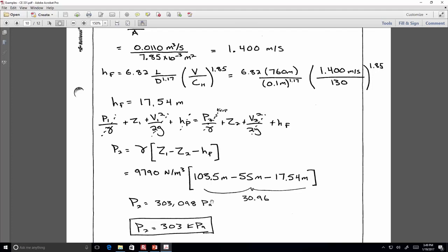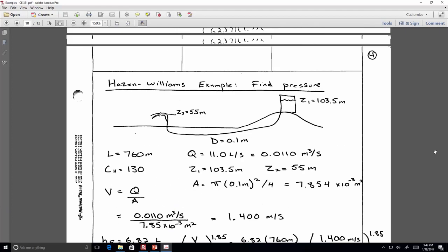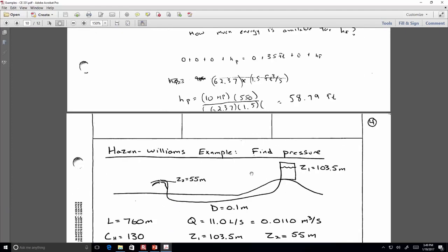I know in fluids you told us to assume 9810. Now where this is outside, are we supposed to assume 9790? Well, as long as you just state what assumption you're making, that's fine. There are different arguments to be made. The water coming out of groundwater, or out of a pipe that's underground, is probably going to be pretty cool, maybe around 55 or 60 degrees, so you could look up the unit weight for that. The 9790 corresponds to a little bit warmer water, and I think the thinking there is it's in a tank, so it's warm from having been in the ambient air.